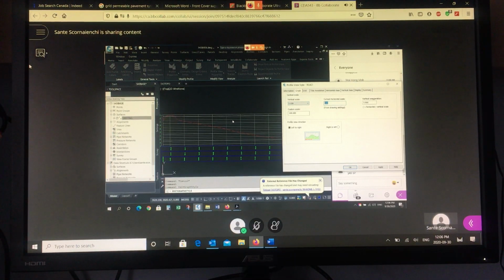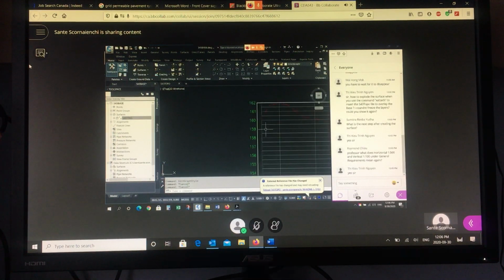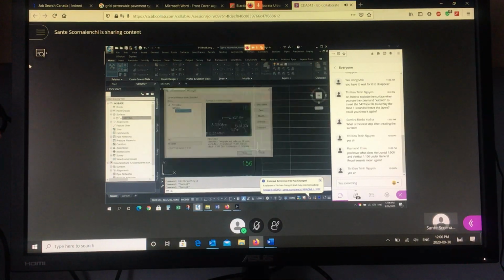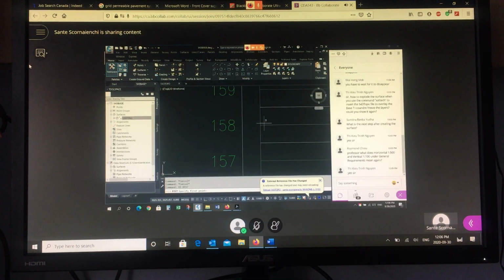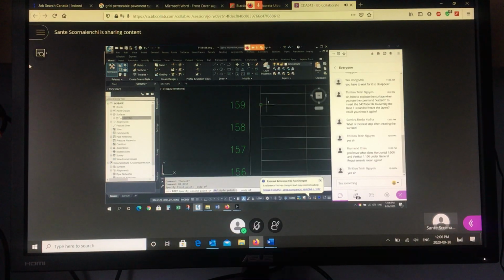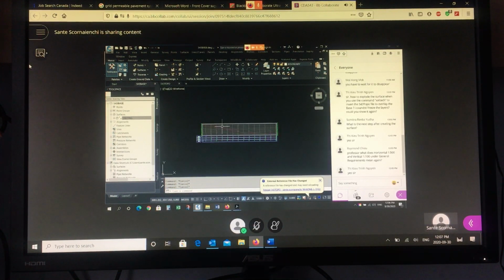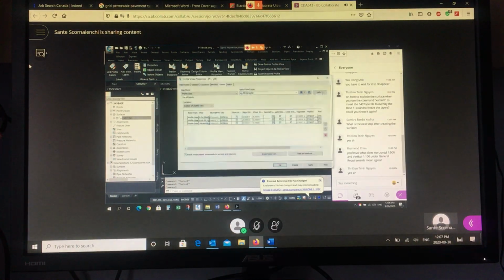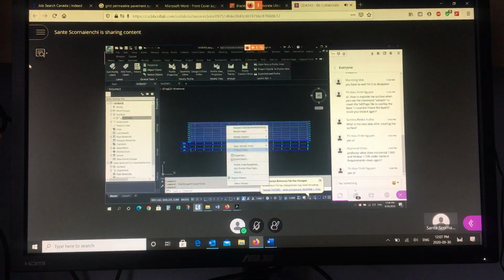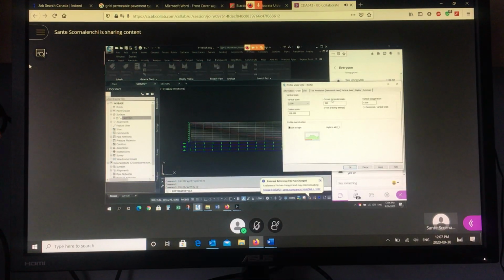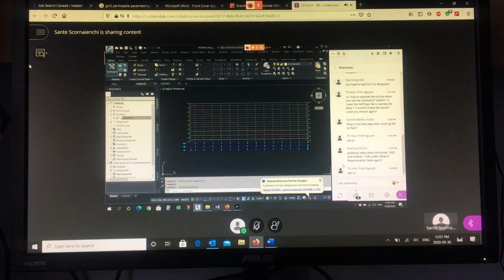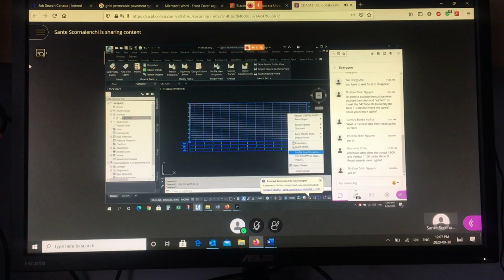So if you measure a distance from 158 to 159, that represents a meter. That's actually 5 times. It's multiplied 5 times. Okay, I can change it, right? Don't do this. I can change the style, right? Just so you know, instead of 5, I can make it 10 times bigger. Watch, it's going to get twice as big. I've stretched it 10 times. Okay? It's redrawing everything. That's the beauty of the database. I haven't changed the data. I'm just changing how I see it.